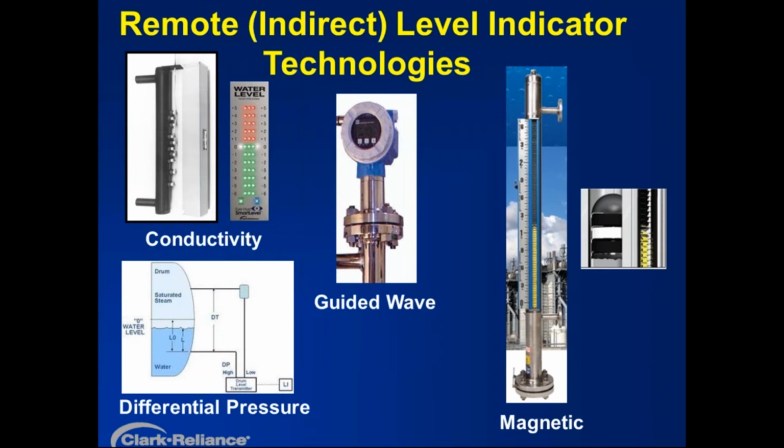If the float is removed and appears to be squeaky clean, you've got excellent water quality and thereby not have an issue. But there's a wide variety of boilers in the marketplace. Sliding pressures, operating pressures can have an effect on the level reading because the float is designed for the specific gravity of the water that it's being used in. And we have a number of users report these things work very well if they run at steady pressures. The code, however, does have a 900-pound limit for the use of magnetic level gauges, and a few more items that I'll describe a few slides down further.